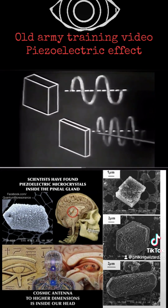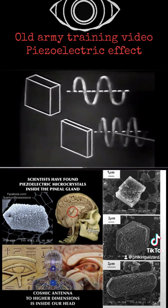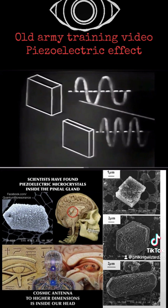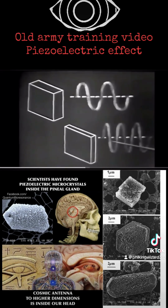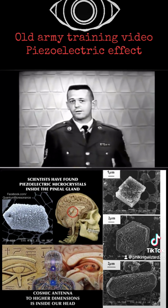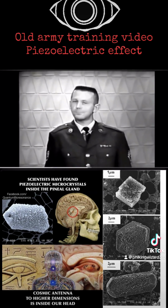We're indicating here that the vibration, or the frequency, of this thinner cut is greater than this cut. Now this will always hold true: the thinner the crystal cut, the higher the frequency of oscillation. Now there are a few other crystal cuts with better frequency stability, but these will not be discussed in this